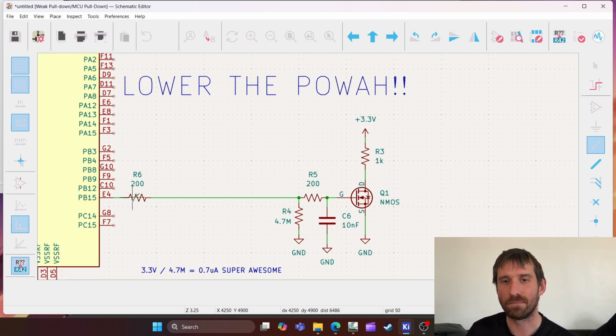At say 100 kilohertz, it doesn't take that much parasitic inductance at all to make this huge. So we just can't rely on any kind of pull up or pull down here. We've got to do it near here. That way we can knock out all this noise and it all goes to the right place, which is not into the gate so it accidentally turns on.